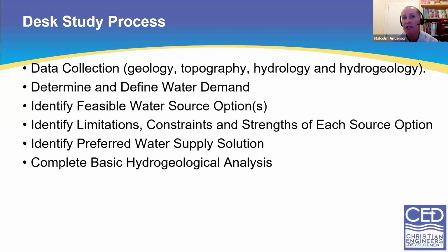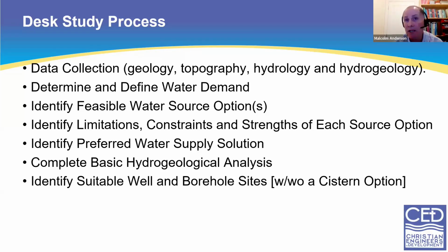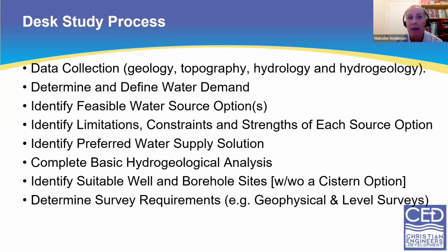Now, most of those things can be done at the desk study level. Similarly, at the desk study level, we can do the basic hydrogeological analysis and identify suitable well sites within the site, where we want to go and where we don't want to go. And we can then make a preliminary assessment of whether we're going to need geophysics and leveling surveys and what have you.